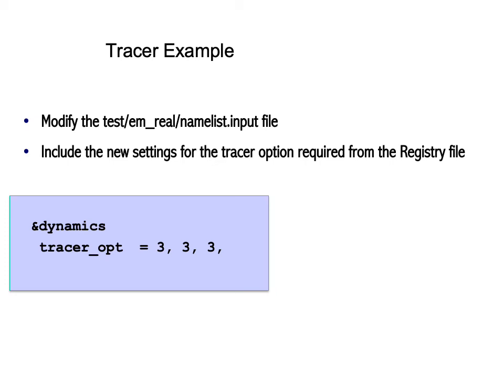So there's a 2-line change inside of the registry. The first is to declare that we have a new 3D array plume that's part of the 4D array tracer. We have a package set up which maps or associates the tracer option equal to 3 to the particular 3D array plume that we are interested in. And we have a do loop source code change that we have to put in the solver, and simply every single time step we add a source term over Fukushima.